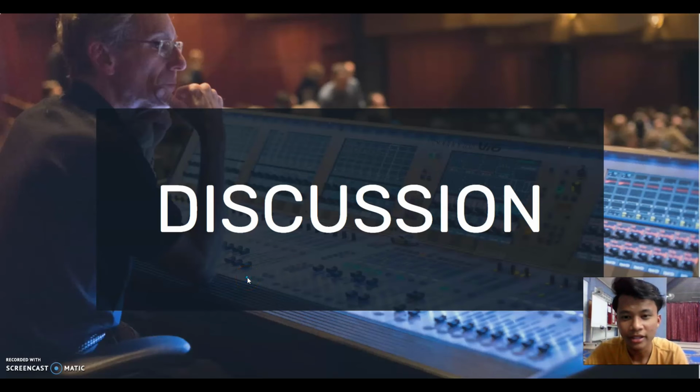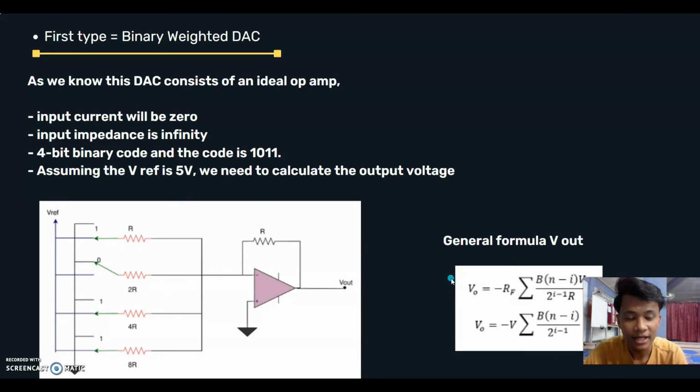Hi and hello everyone. Now we move to the discussion part. As we know, there are two types of DAC, which are binary weighted DAC and R2R ladder DAC. As we know, this DAC consists of an ideal op-amp. So when we use an ideal op-amp, there are two rules: input current will be 0 and input impedance is infinity. So for further details, I will give some example of calculation.